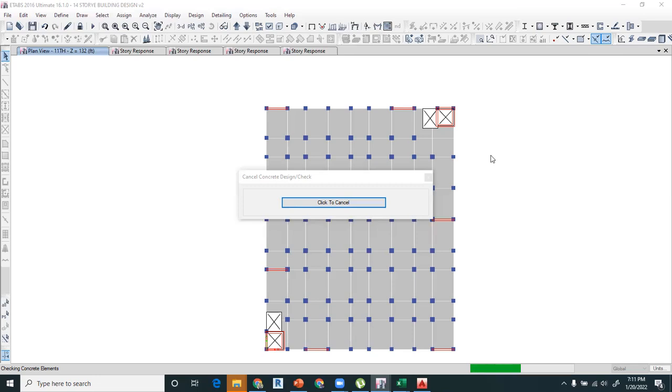Is it possible to consider a 7-story or 10-story building without earthquake in any country, in any place? Is it possible to design with no earthquake? Normally, the earthquake is unpredictable. You can see that many of the places that were considered as zone 2B, now in the new code in Pakistan, are considered as zone 3, because many of the earthquakes have surprised the engineers that they were not expecting that much magnitude earthquake in that region, but it happened.